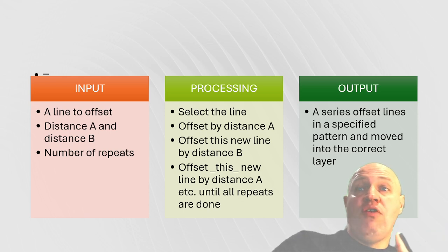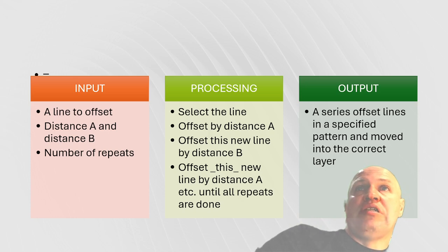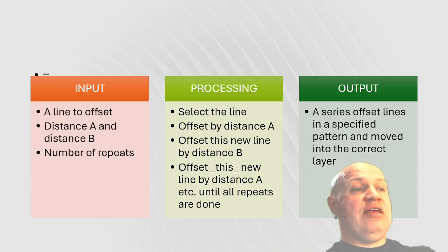This general pattern that we're asking for here is something that you could then write a Dynamo script for, or a Python routine to wrap up into pyRevit, or a Grasshopper script to run in Rhino. The point is, today I'm demonstrating it with one tool, but the same plan, the same algorithm, if you like, can be used with other things.